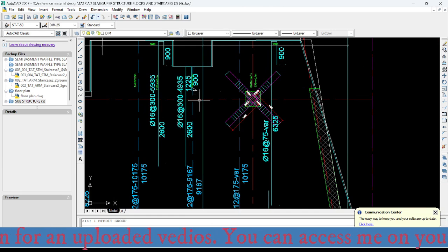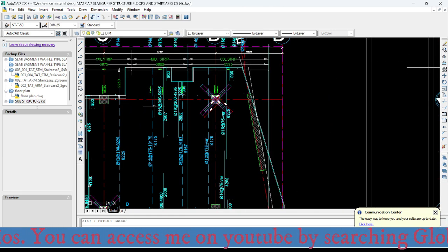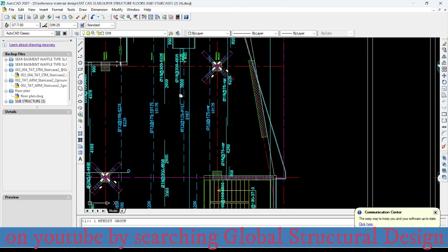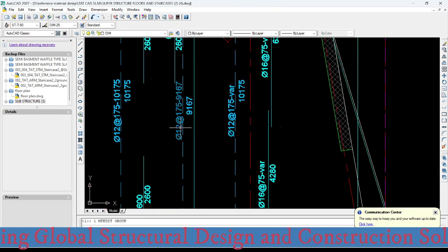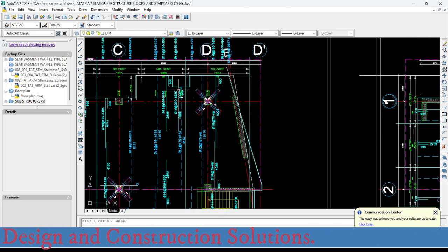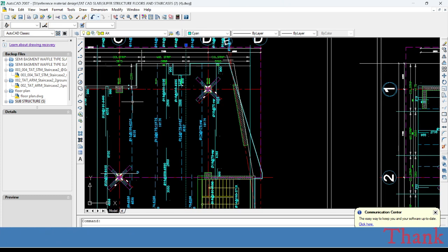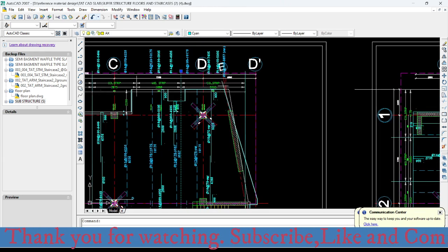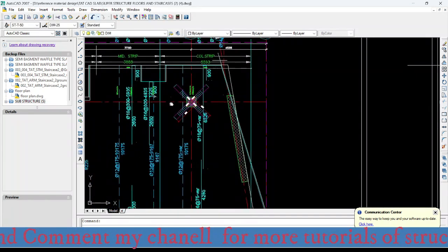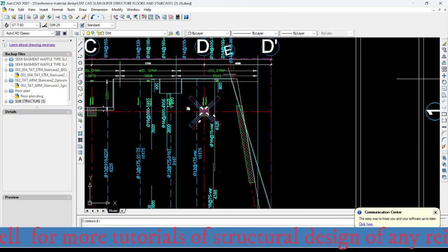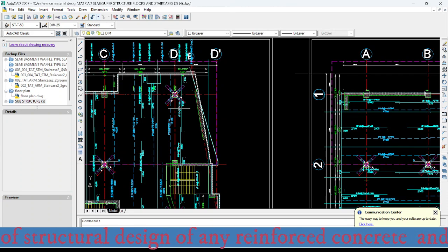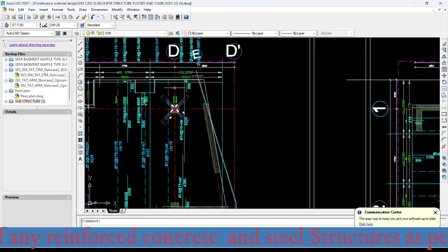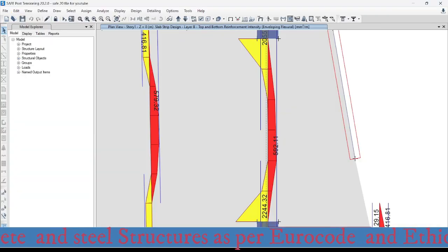This one is also similar because this portion is included under the middle strip portion of this one. So here I can use the same bottom reinforcement. The only difference is the length of the bar here because there is an offset here. So the portion from here up to here is included as the middle strip. Okay, now let me go to the last column strip here. This is the last column strip. So now let me detail the negative reinforcement first.